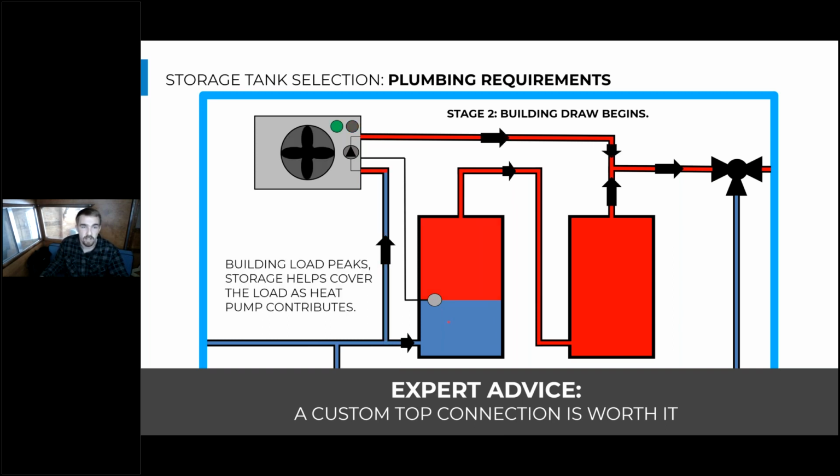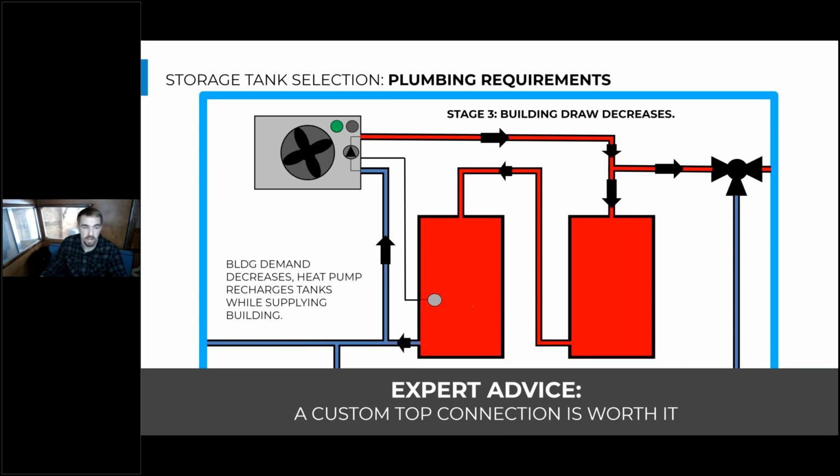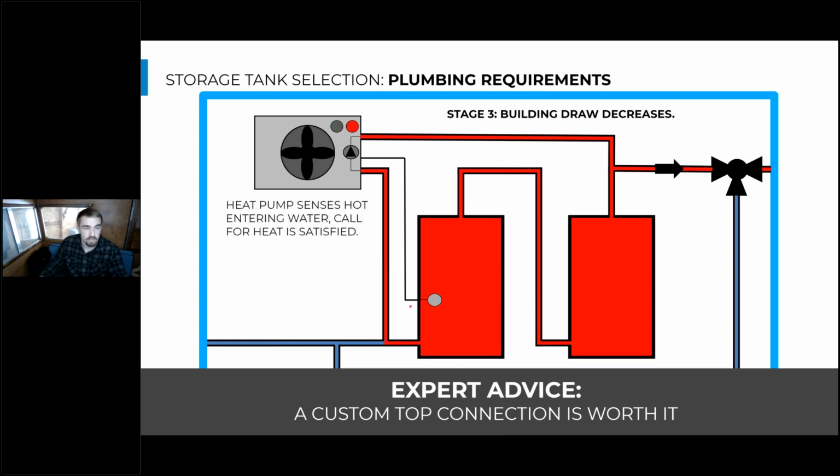If the heat pump's not keeping up with the building draw and more water is being drawn out of the tanks than the heat pump can supply, this storage still continues to draw down until this peak load in the building subsides. The heat pump can then recharge the storage after everyone's done with their showers and there's lower usage. So then we have the completion of the cycle again, because the heat pump's been allowed to recharge this storage and turn off, seeing that high entering water temperature.